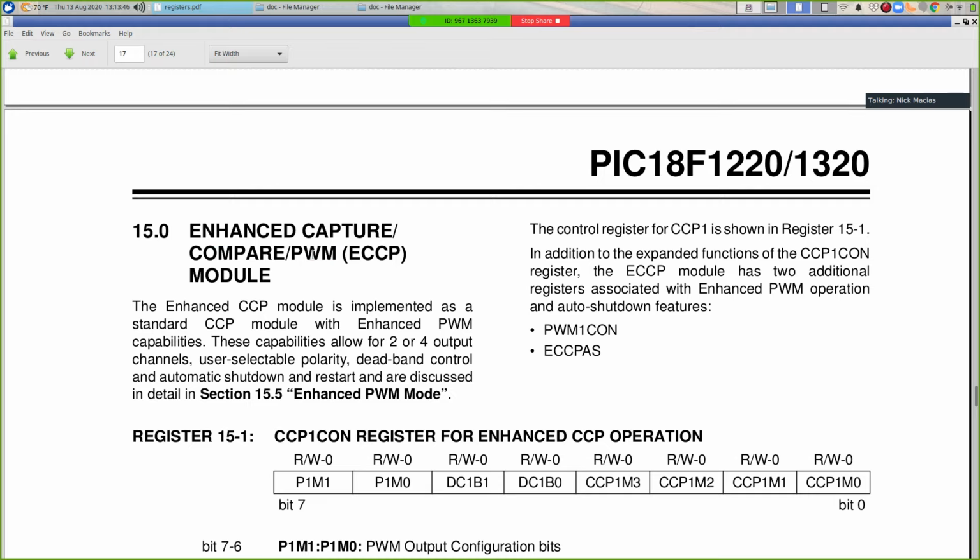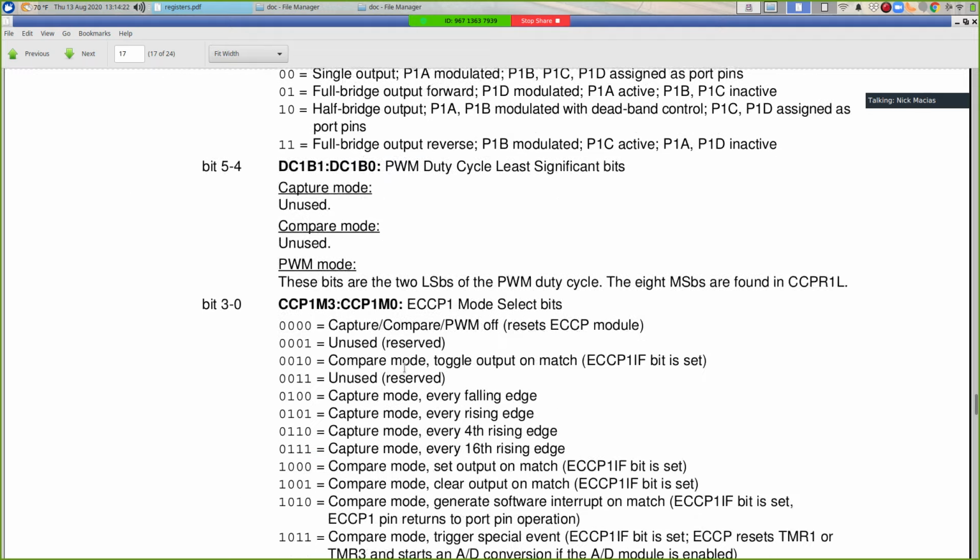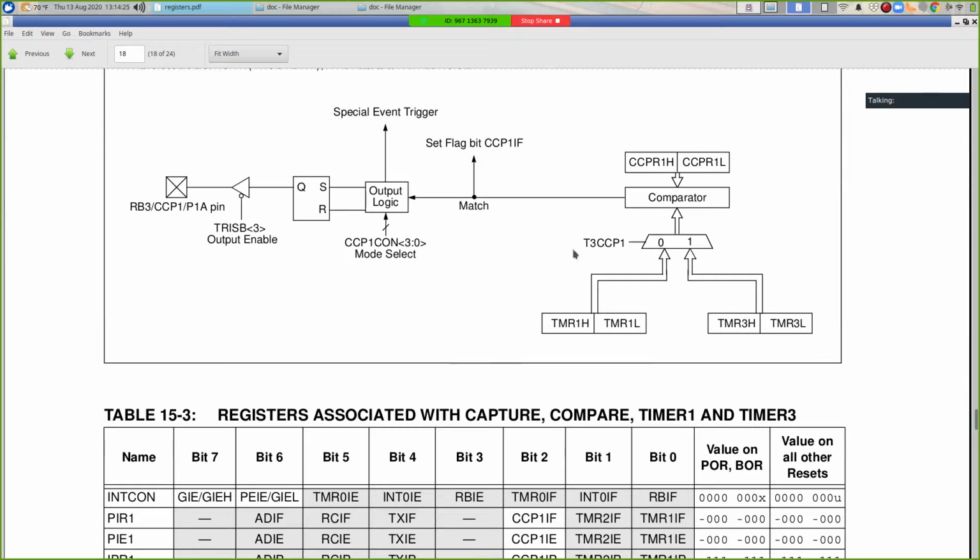Now, I don't want you to use this for Lab 5. In Lab 5, you have to generate these signals by hand, the way we've been talking. But independent of Lab 5, I want to go through this system. Basically, we can pick a duty cycle and have the PIC automatically generate an output with that duty cycle. And we do it using timer 2. We set timer 2 to interrupt at whatever period we want the output waveform to have. And the duty cycle is controlled by using these registers, CCPR1L and CCPR1H.